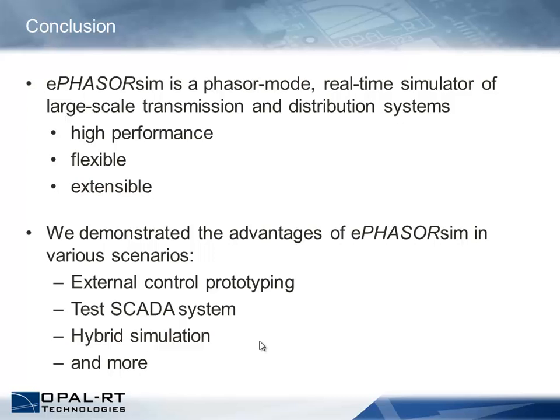People want to use that feature more on their distribution side, but it could model the complete system using that feature. John is absolutely correct. I take it back. We do have a pi-line model for lines, which could very well be used for transmission lines. We have three-phase loads, which could be fully unbalanced, so it could be used in a transmission context. For example, if you have loads, lines, what else do we need? We have a voltage source in which you could specify them unbalanced. I think the only thing we're missing right now today is a generator model that would be unbalanced. A machine.